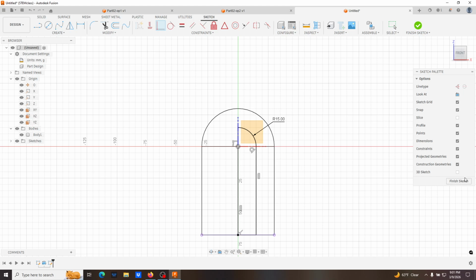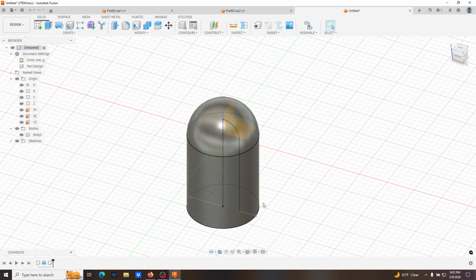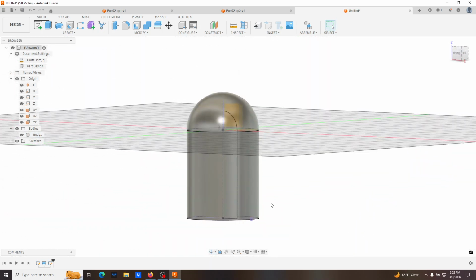And this is kind of cool just for design intent, because if I made this directly 85 and I wanted to change this, I'd have to change it in two places. But since I have it linked to that, if I go back and I change it, it will go from there. So now I have this sketch inside of, and we kind of see how that goes.